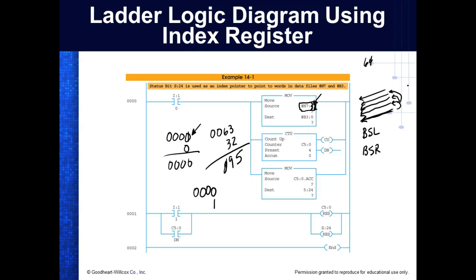So this is the way we indicate index addressing. We come up here and start off with a hashtag. What's the S24? That's the index register. S24 is the index register. Okay, so then that's where we would load S24. The 1100 doesn't give you the ability to change the index register, so you start with 0. But I think the SLC 504 gives you the ability to put whatever you want in the index register. This guy right here, I'd have to look and see what's available.